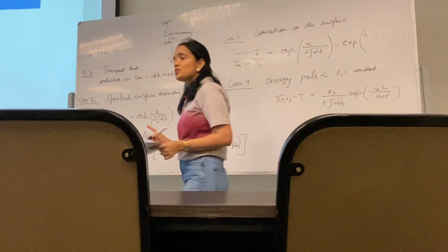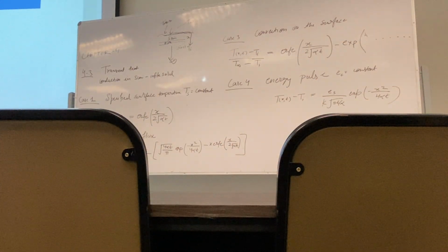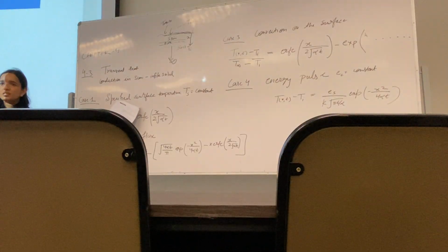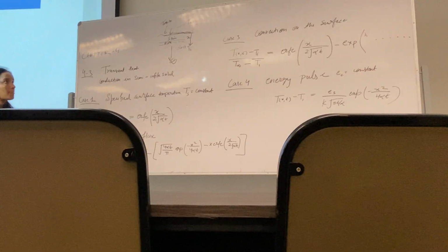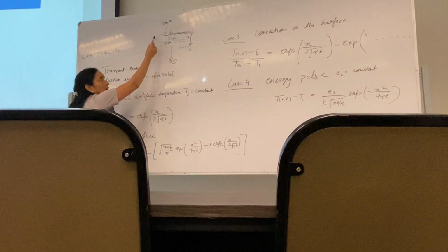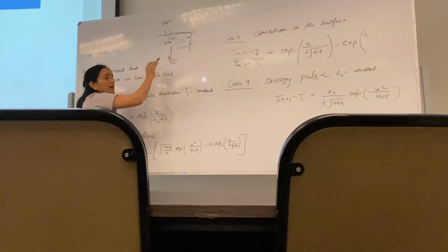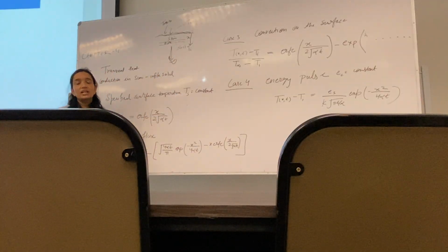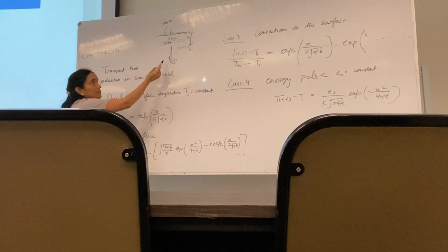Okay. Semi-infinite solid, you will have 4 cases. All numericals are based on 4 cases. Either your surface temperature is given, or heat flux is given on the surface. Semi-infinite solids are like this. They extend in the infinity direction. This is an example of an earth.